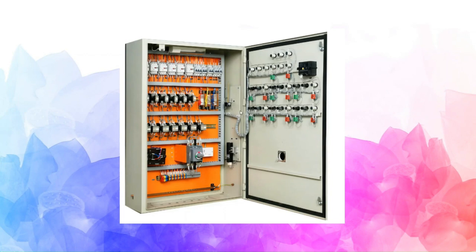Now look into this. There is no compartment here. I mean, these are MPCBs. So definitely it is supplying to some of the motors. It is providing power supply to the motors, but it is not in separate cubicle. Altogether all the things are in only one compartment. So it is called non-compartmentalized. So look, these are all contactors here.